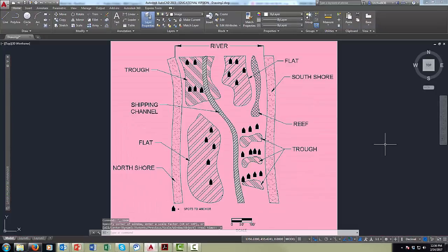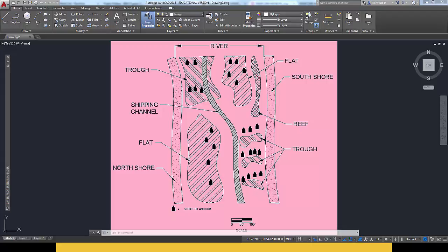Now the scale that you actually enter for your drawing is going to depend on how you insert it. So what you have to do is insert it, use the distance command to measure how far it is across the scale, compute the amount you need to expand the drawing, and then scale it up that amount. Now that I've imported this image into my drawing and scaled it properly, I can just draw right over the top of the current image in AutoCAD, and when I'm done, everything will be to the proper scale.